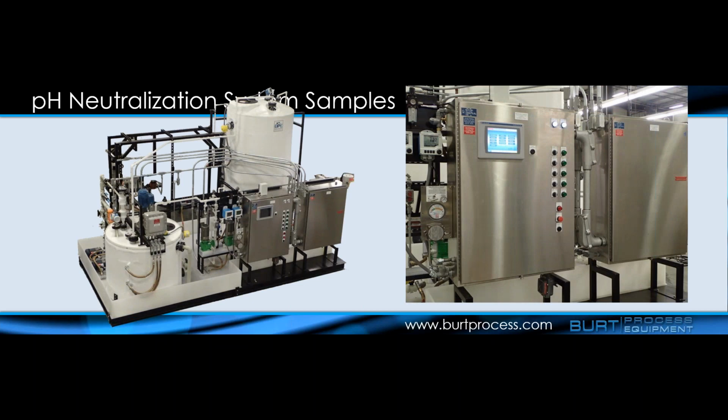you can get into more process-based systems. This is actually a hazardous location pH adjustment system, whereby you have your equalization tank that then feeds into a treatment vessel. They were actually treating very strong waste here with hydrochloric acid. This one's also located outside, although it is Class 1 Div 2, so a lot of this is designed a little bit differently. You do have heat tracing in these cases. So again, it's all based on the same principles we've talked about today.